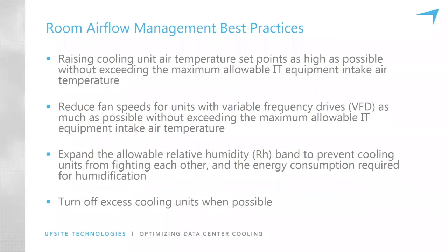So the best practices of room airflow management and cooling optimization are raising cooling unit air temperature set points as high as possible without exceeding the maximum allowable IT equipment intake air temperatures. There's been a lot of controversy in the industry about raising temperatures. People say, I don't want to raise the inlet temperature to my IT equipment for various reasons. But if airflow management is really done thoroughly, then intake temperatures to the IT equipment are reduced. Then the set points can be raised and the intake temperatures return to where they were before, but with higher set points on the cooling units. And then we have more efficient cooling units.